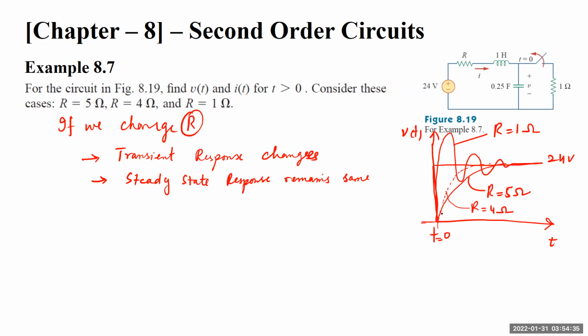So the system follows the step input, and it will take some time for the system to reach its steady state. In case we have a very low resistance, the system will have an underdamped response, and it will overshoot, and there will be some ripples until it dies down and approaches the steady state. If we have a very high resistance, it means that the system is overdamped.